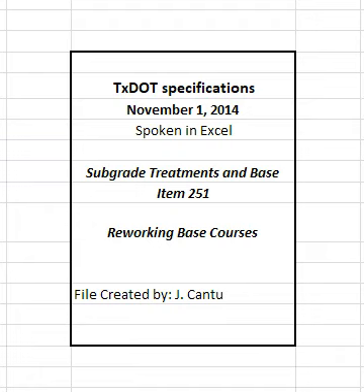5.3 Cubic yard in vehicle. By the cubic yard of salvaged material in vehicles as delivered at the stockpile. 5.4 Cubic yard in stockpile. By the cubic yard of salvaged material in the final stockpile position by the method of average end areas. 5.5 Cubic yard in original position. By the cubic yard in its original position measured by the method of average end areas.